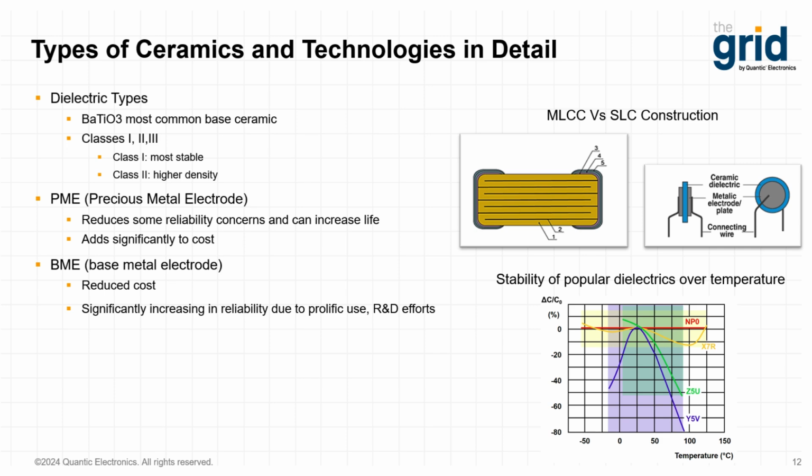SLC is typically used for higher voltage and through-hole required applications. MLCC is the leading ceramic technology. Most all ceramic capacitor SMD chips are multi-layer ceramic. The multiple layers allow for a smaller footprint on the board, and higher cap density. The surface mount configuration also eliminates any parasitic losses associated with long leads, and surface mounting also allows for using both sides of the board.